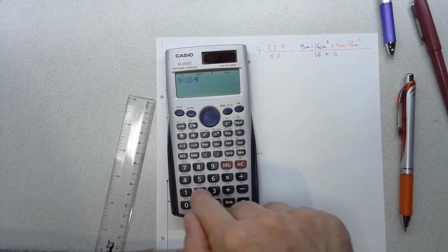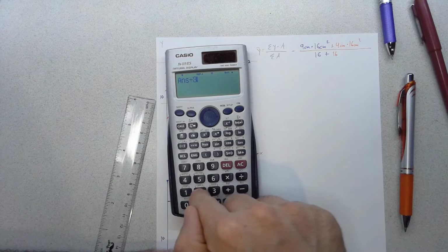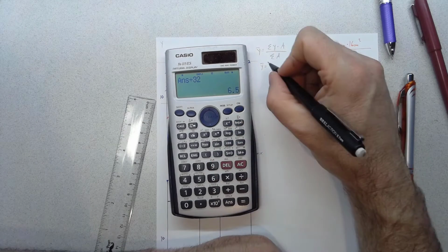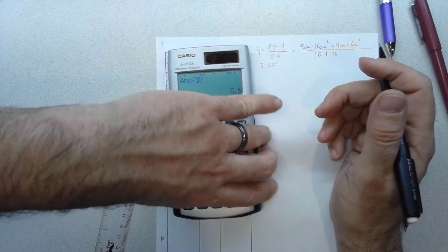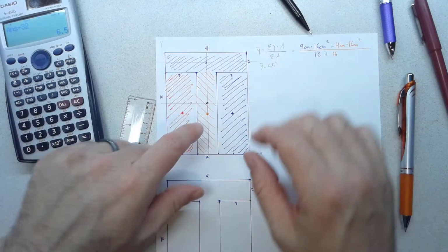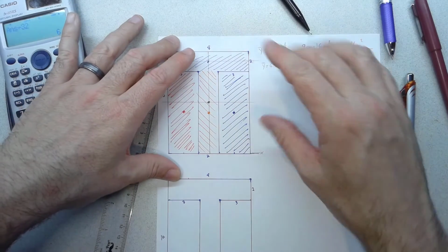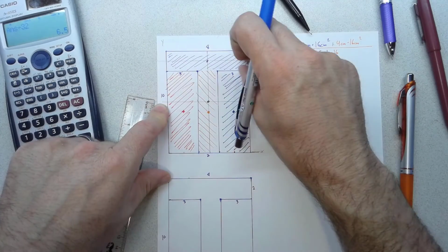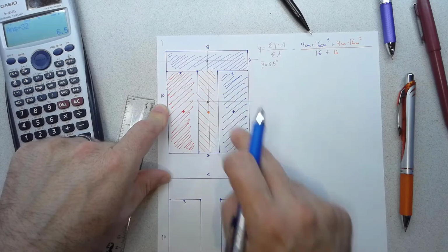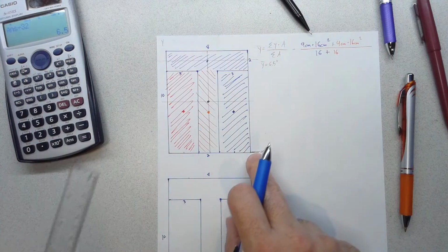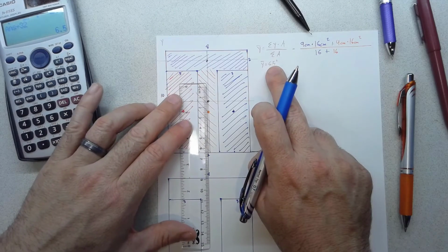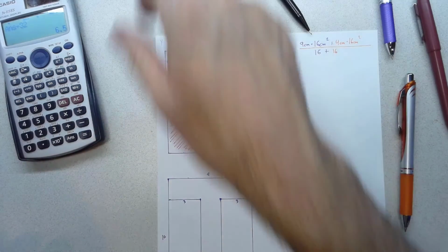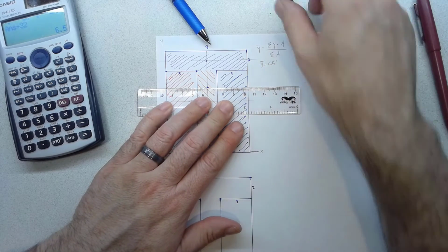Okay, so let's figure out what that comes out to. 9 times 16 plus 4 times 16, divided by 32. So y bar is equal to 6.5 inches. Originally, the neutral axis of a big rectangle 8 by 10 would have been 5 inches. Now we have found our composite y bar for this final T shape is at 6.5 inches up from my reference. I did 9 and 4, both off of the bottom, so that's where I'm measuring my 6.5 from. So I come up 6.5 from the bottom, and right there is my new centroid of the composite shape. This is the neutral axis for my composite shape.